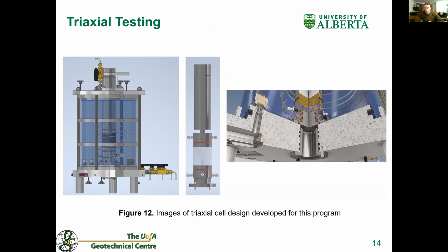The triaxial program will consist of gathering internal pore pressure measurements using a conventional triaxial test with microfiber optic sensors embedded into the sample. The purpose of this task is to validate the internal pore pressure readings collected using microfiber optic sensors, to develop a procedure for sample saturation and consolidation during direct shear testing, and to further investigate the anisotropic pore pressure response of overconsolidated bedded materials using internal pore water pressure measurements.